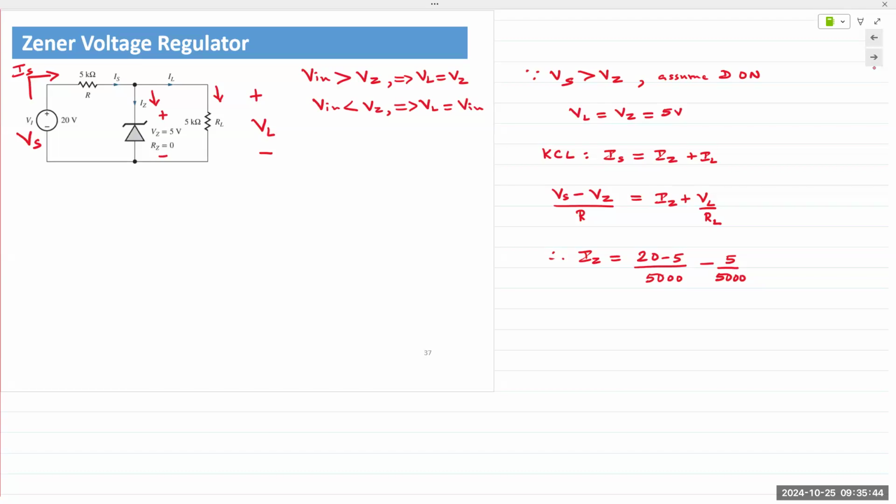Okay, so hypothetically speaking, if we just wanted to connect a Zener diode and power the Arduino that way. It should work. There are a few other considerations, meaning the load resistor, voltage coming into the Zener diode, the current coming in from the source, but theoretically it should just work. That's the answer. Sorry for going on a tangent. But in general, as long as Vin is greater than Vz, it should just work. But we'll talk a little bit about the point of connecting Zener in parallel with the resistor and what other factors can affect it.